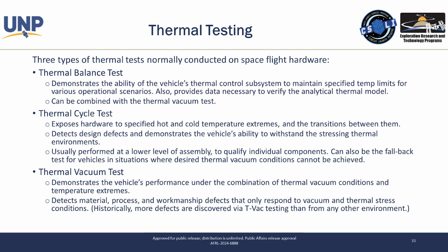Thermal testing is extremely important and very difficult to design for without many, many years of very detailed thermal analysis that'll still end up being wrong. So this is where we say, I can shed all of the heat or keep as much of the heat as I need to when I'm in vacuum, both in day and night, and keep all of my systems operating. Batteries are by far the most constraining in almost all systems. Batteries really don't like to be cold. And so making sure you can keep them warm enough, but without overheating all of your other components and melting solder and things falling off is the name of the game.